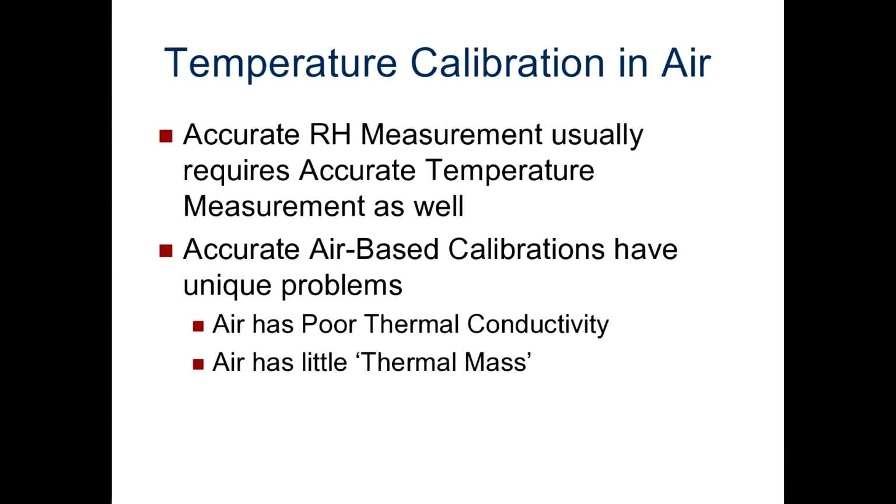Accurate air-based calibrations have unique problems because air has very little thermal mass and is a poor temperature conductor. As a result, when we try to achieve good calibrations in air, we get temperature gradients that must be compensated for. Again, these can certainly be done, but it requires specialized setups in order to achieve it.